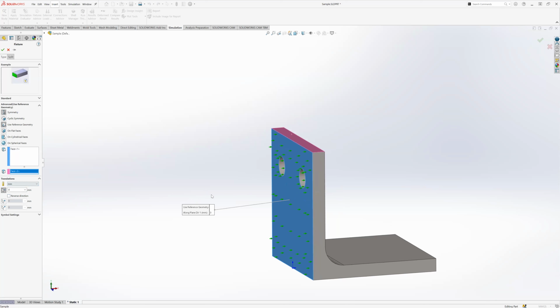So this would be the same as a roller slider. When you put a displacement of 0, that's essentially restraining all translation in that direction. Another thing this is also very useful for is, a lot of times, especially when you have a part, sometimes you don't know the actual force that's applied to a part. You know how much it deflects, though. A lot of times you get that with strain gauges. So if you have a strain gauge, you can obviously calculate the displacement from that. So when you have that, you can actually specify a certain displacement in place of force.